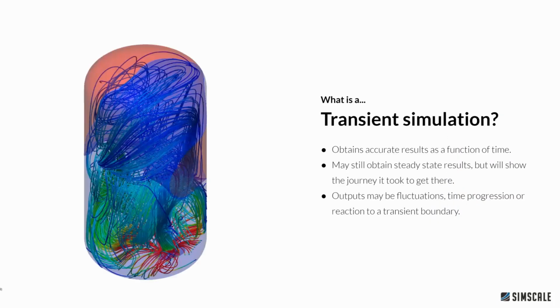It comes on to the question, what is a transient simulation? Why do we need it? Well, typically we have two types of simulation. We've got steady-state simulation, in which we assume that the results are going to accelerate towards a steady state. By that I mean, if you were to drag an aerofoil through the air, you're going to measure the lift on it, and eventually it's going to get to the point where you're going to say, okay, it's steady at some sort of lift. And that is a steady state. It has reached a steady state. It's not going to change over time.